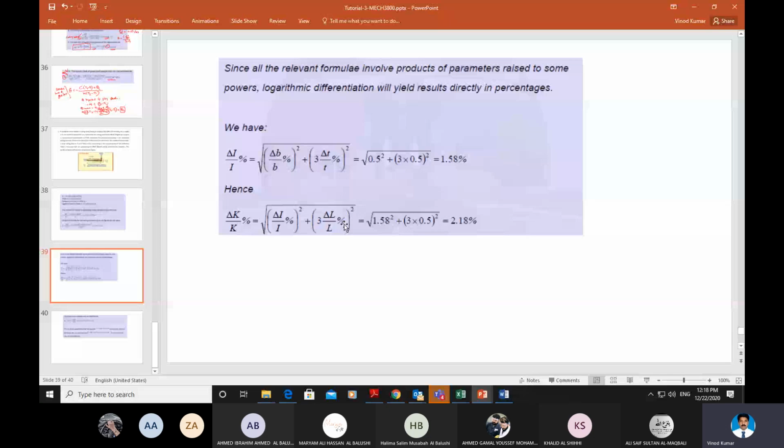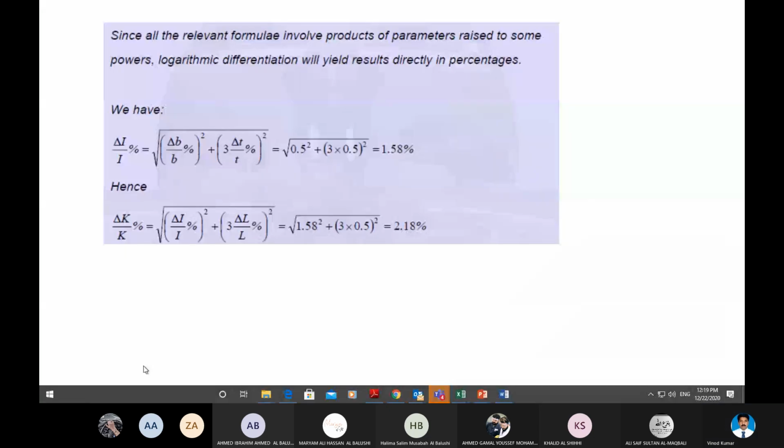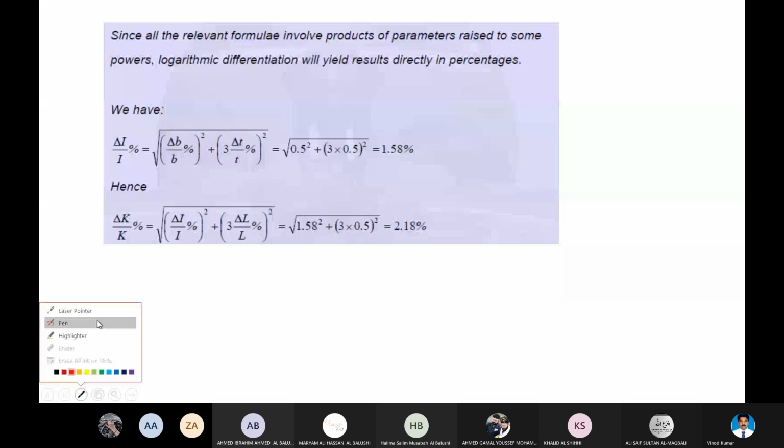So I'll explain what we have. We have modulus of elasticity, width, thickness. We calculated I as B H cube over 12, converting millimeter to meter. We calculated the spring constant, 3 E I over L cube for a rectangular section.